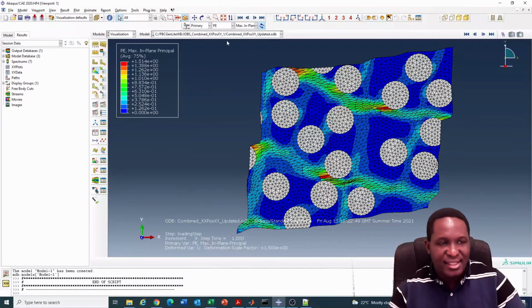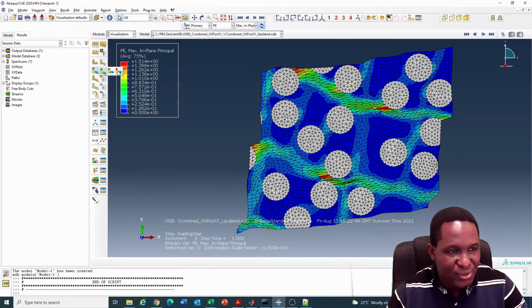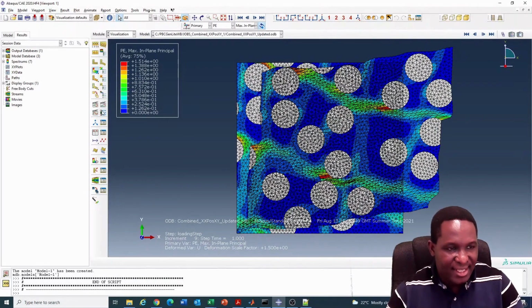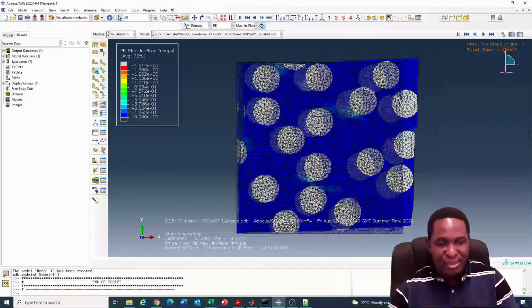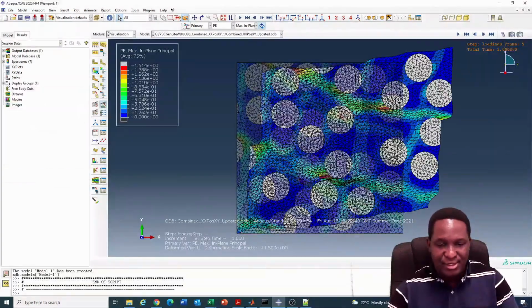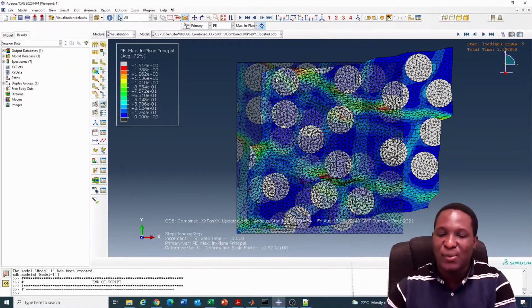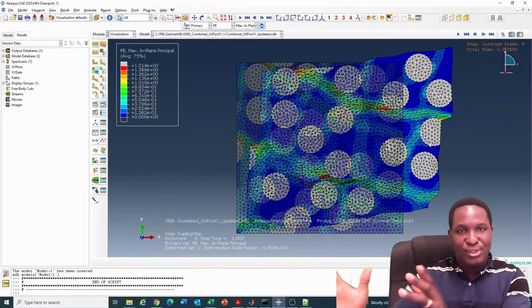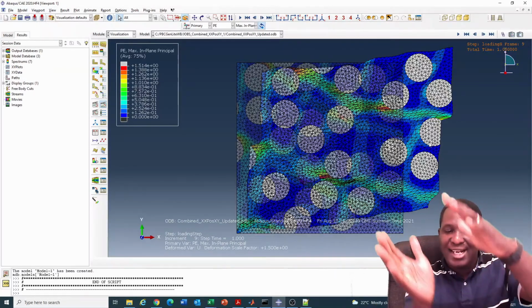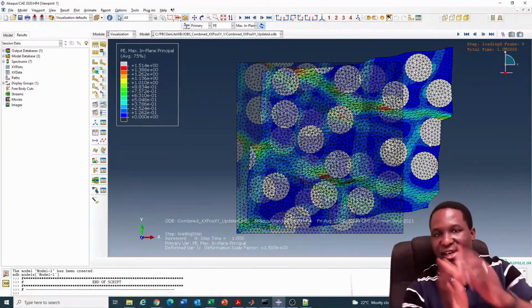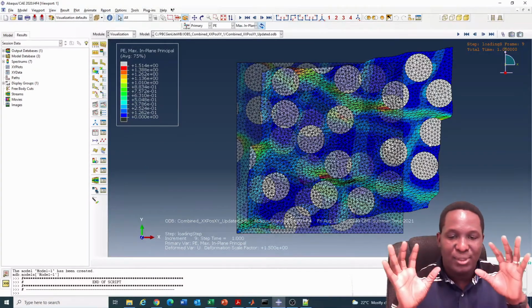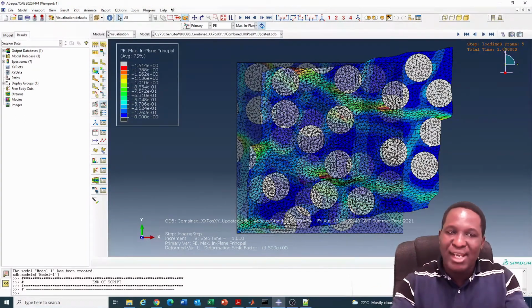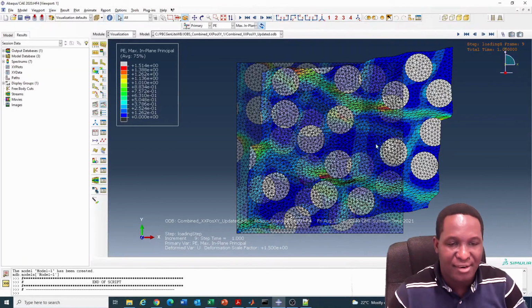So this basically tells you, especially if you compare the two together, what we are looking at here is a deformation where you have a shear loading due to this pulling in this up direction and pulling in that direction, as well as the tensile loading, because this front end is being pulled. So you end up with the front end being pulled, and also you get the classic shear deformation, which is this kind of angular behavior. So that tells you that this is really a combined loading scenario, and we've got our result for that.